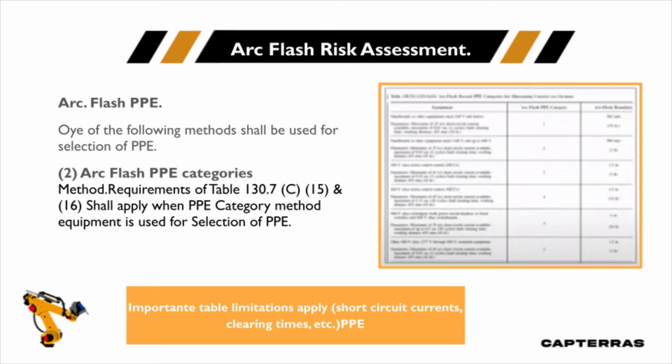But the key thing here is, don't wait for your study to be done to wear PPE. Start somewhere. Start, if you need be, in the tables, and start today. Because the longer we wait, the more possible we expose someone to one of these terrible, terrible arc flash incidents.